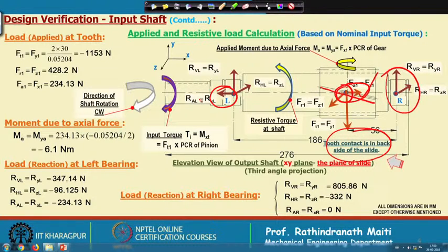Now, the question is that sometimes it is a little confusing. Actually, if we consider that the bearing at this end is fixed, and the applied load is pulling, then the load the bearing offers to the shaft is in the opposite direction. That means the bearing is pulling the shaft in the left direction. That is why the sign has become like this. Students used to ask, sir, why is it like this on the bearing? You have to visualize at this point.